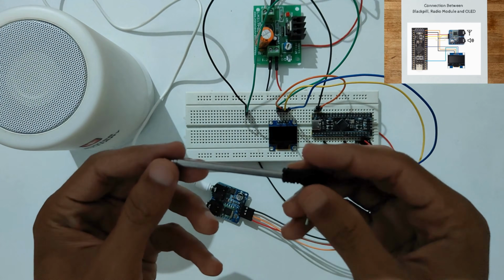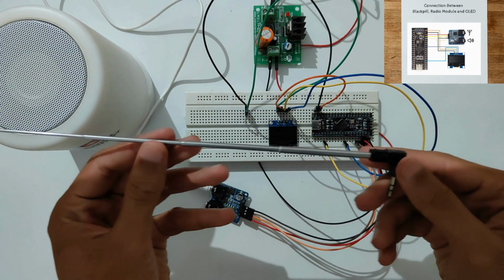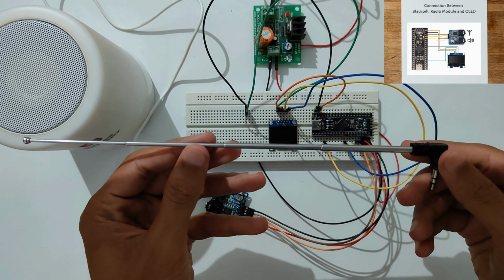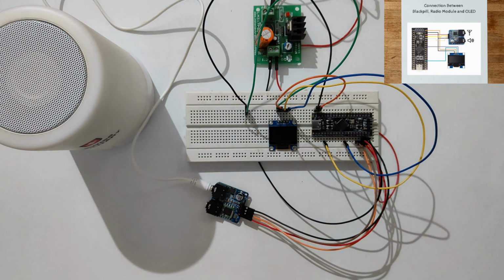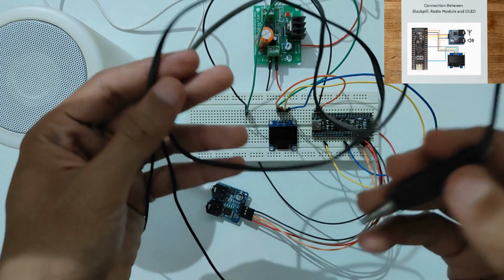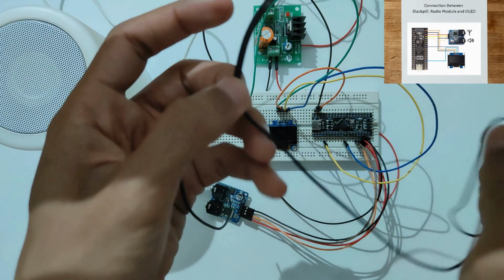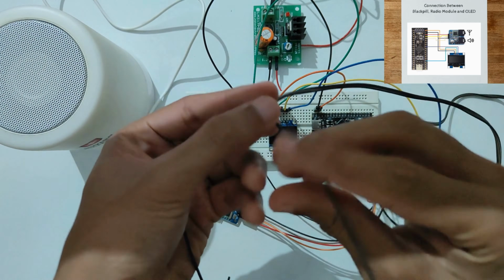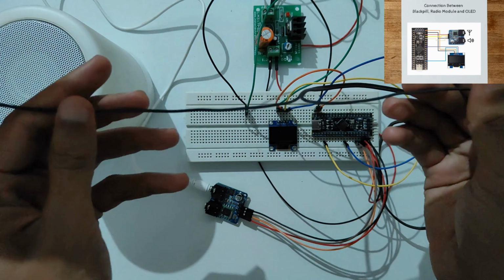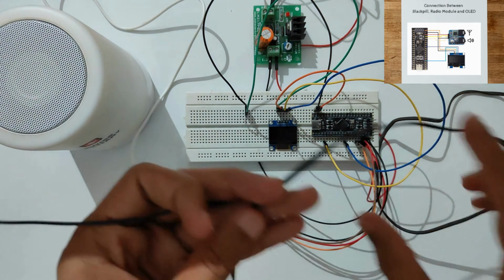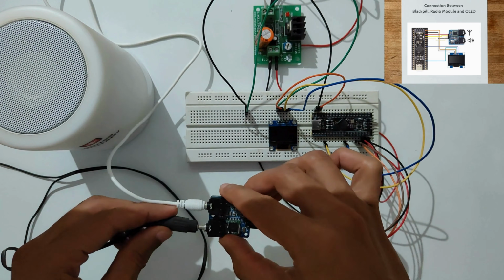The radio module also comes with a 25 cm antenna, but the signal strength is poor. We need at least a 75 cm antenna for good reception. If you don't have one, you can use an insulated copper wire or an old aux cable from a speaker. I have used an aux cable from an old speaker. Cut it and connect it in a T shape for better signal reception. Now, connect this aux cable to the radio module.